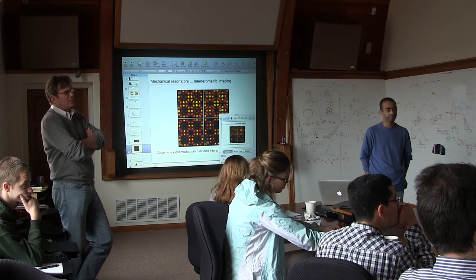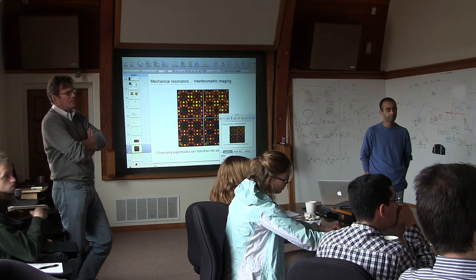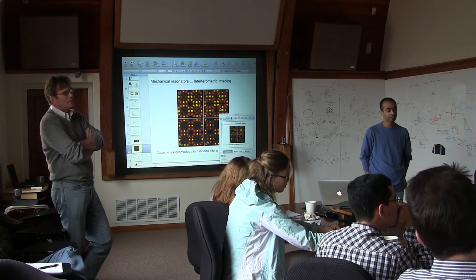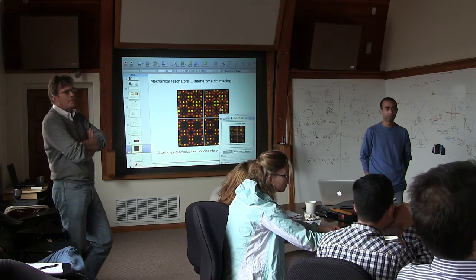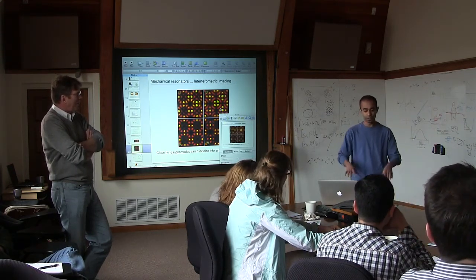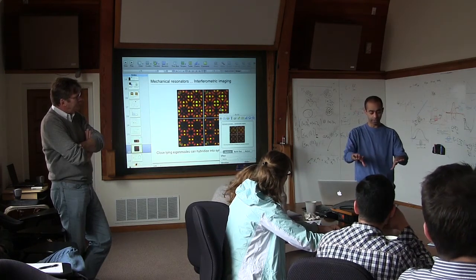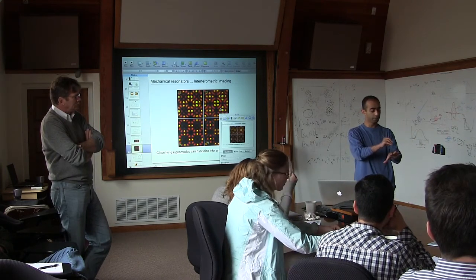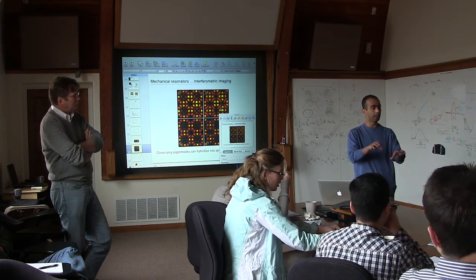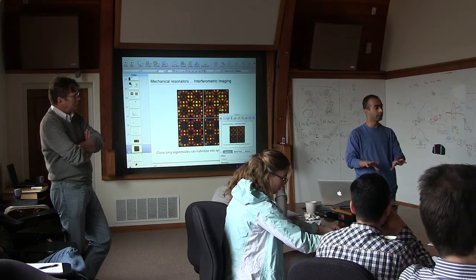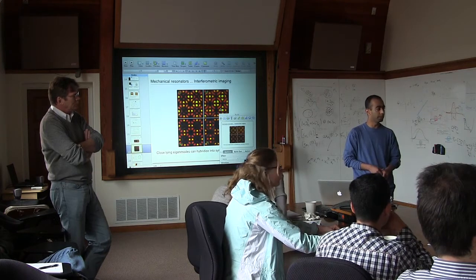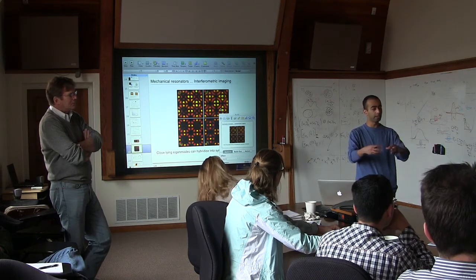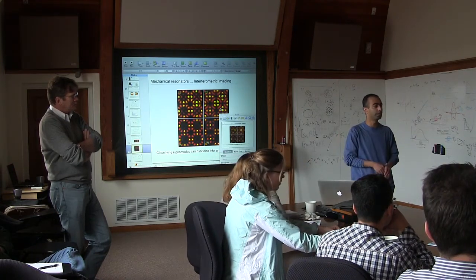So you can do some effective mass engineering. So basically do symmetry in such a way that we have one mode in the vicinity, and you exclude a certain frequency range. Keith also had this interesting idea of saying, can you just, even if you can't, because it's under very high tensile stress, you can't really punch holes in this membrane and create arbitrary patterns. But what you can do is do the opposite: you can deposit tiny chunks of matter and weigh some modes down and not the others. And so that would be another way of engineering some mode shapes. The question is, will it really affect the dissipation? If those masses are in the interior, away from the clamps, hopefully they won't change the dissipation too much.